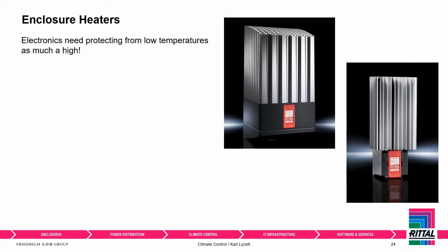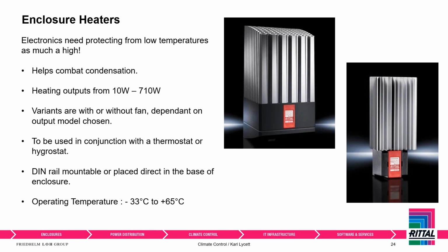Enclosure heaters. So we've spoken a lot about cooling, frankly, because there's always a lot of cooling to be done. But we also need to make considerations about protecting from low temperatures. Again, these are not too sophisticated. They do a job and they're very important. They help combat condensation. Because again, if we go back to our imaginary pump that's working outside, it might turn off at the weekend, and all of a sudden, the temperature starts to plummet inside the enclosure.